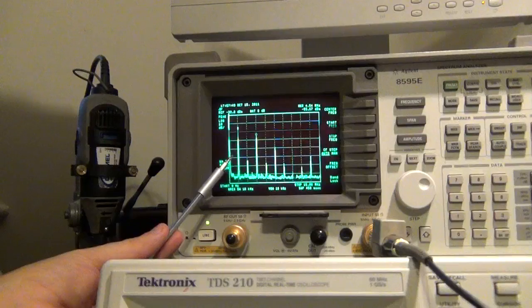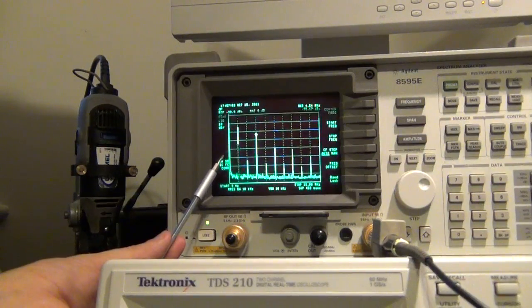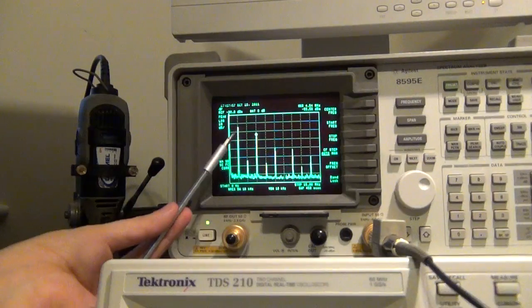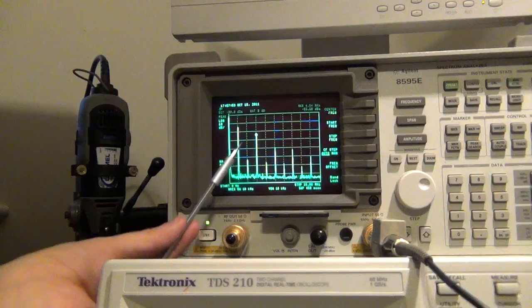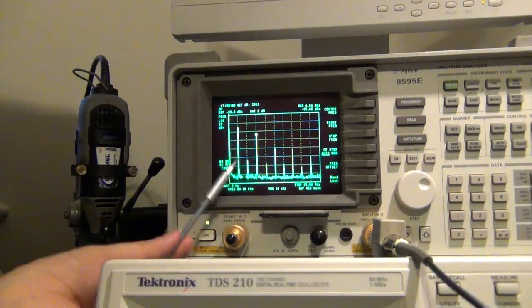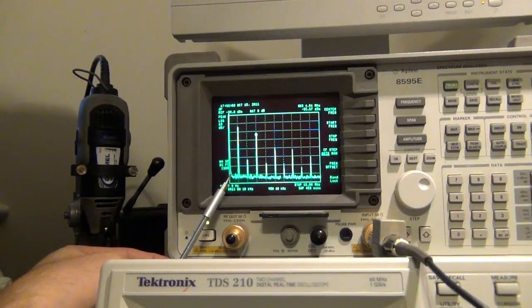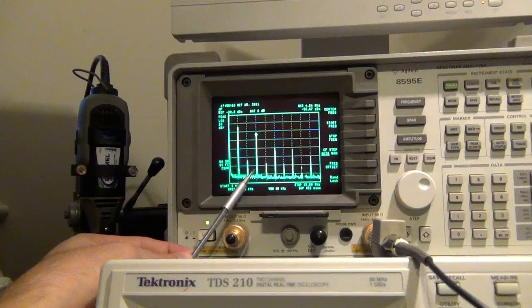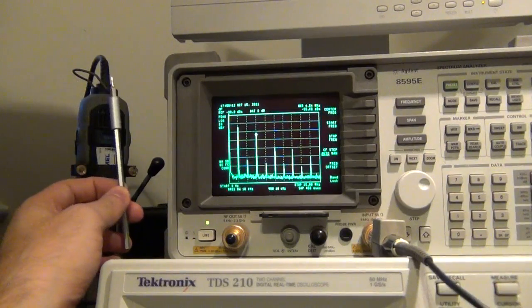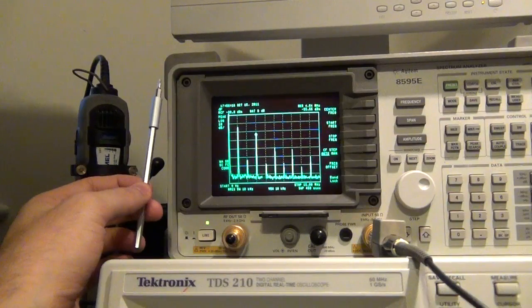So let's say that I have a signal source that's 1.5 megahertz and I need 3 megahertz. Well, I can see that in this signal I have 1.5 megahertz and I also have 3 megahertz signal both present simultaneously. So if I could somehow filter the fundamental tone, I would be left with a signal that is stronger than all the other tones. So I would have a circuit that can triple my frequency.